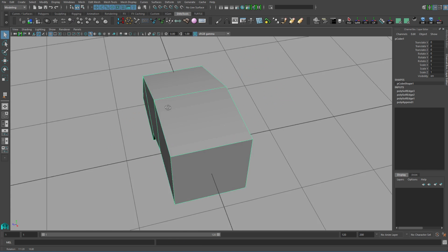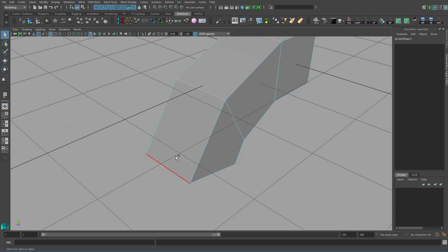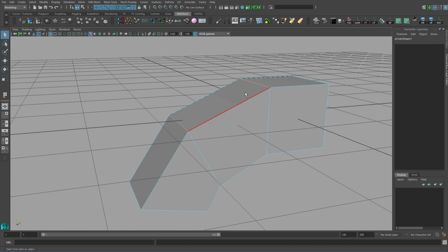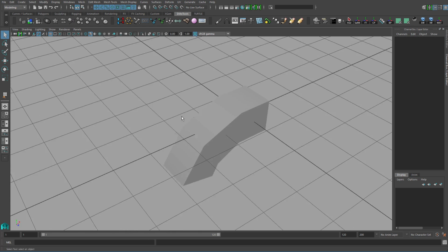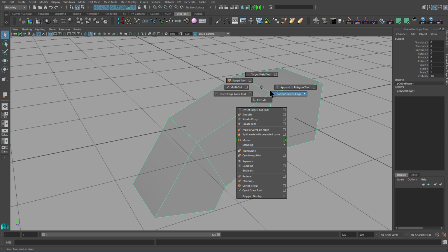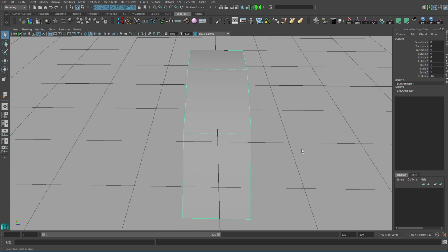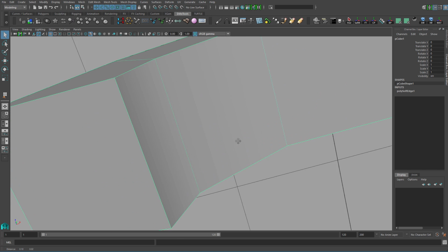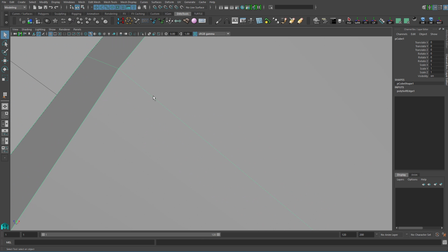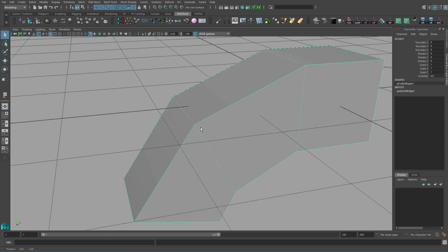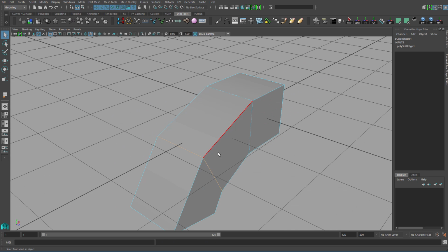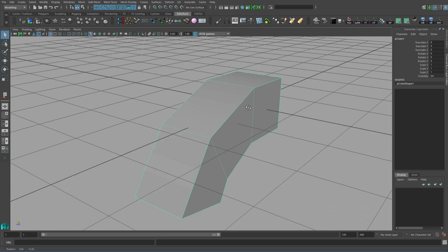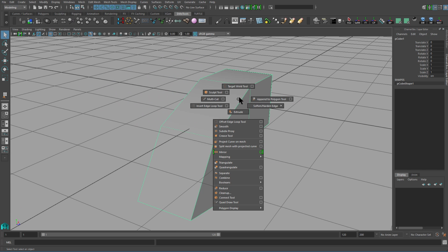It really doesn't matter to our rendering process if we use smooth preview, but if you want to create low polys and you want those edges to be smooth, you can grab those edges and then holding down shift and right mouse button, soften harden edge to make it soft. Okay, so that's that. You can toggle the soft edge display. That will make the softened edge become a dashed line, to indicate that that line is actually a soft edge. Okay, that's insert edge. That's soft and harden edge.